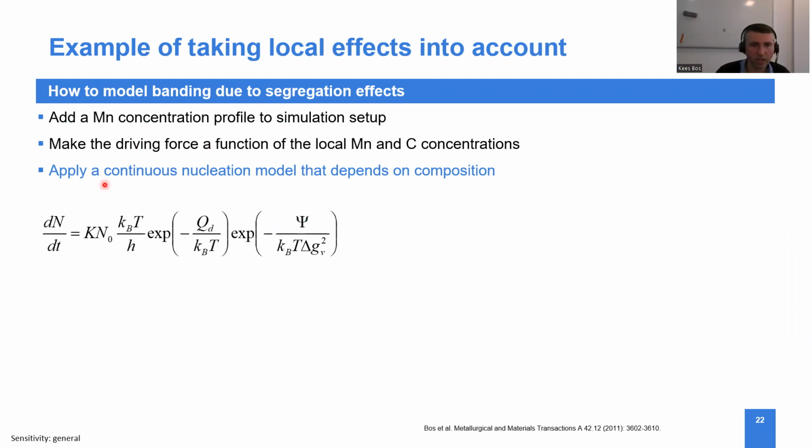So then we get to, I would say, almost a classical nucleation equation, here described in the form I think given by Erik Offerman, where the psi factor is handling the shape and boundary energies of the nucleus, and here we have the chemical driving force.